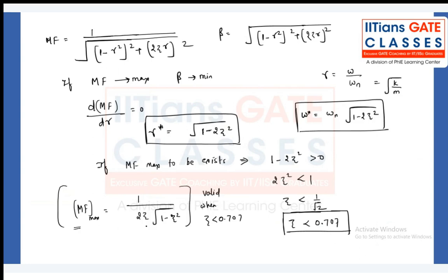All of you have noted down 1.04, right? But that particular formula is not valid for zeta equal to 0.8, because it is only valid for zeta less than 0.707. Why? Because you might be thinking, sir, we are getting 1.04, one something.